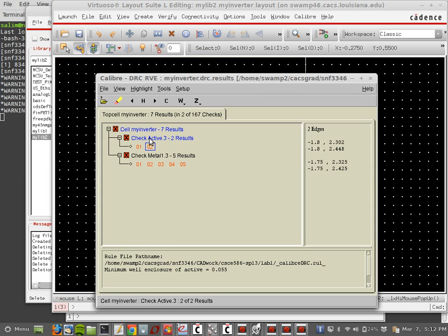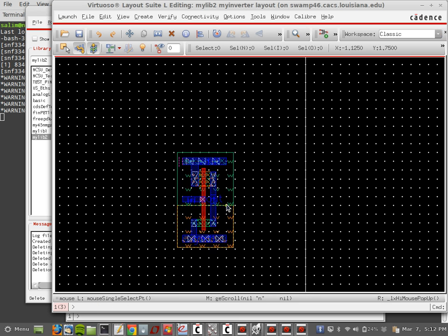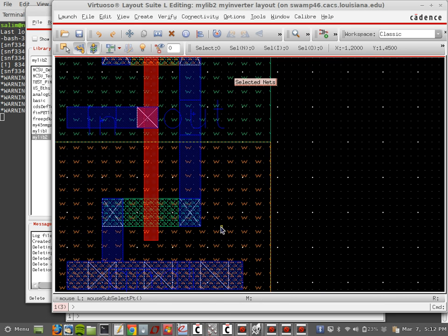So I'm sure now I got rid of these. Now let's look at the metal errors. So here it tells you that metal 1 must extend past contact by 35 nanometer on two opposite sides. And it's the same for all other errors. Okay. What this means is simply that when you have a contact like that, metal 1 should go past the contact by 2 lambdas.